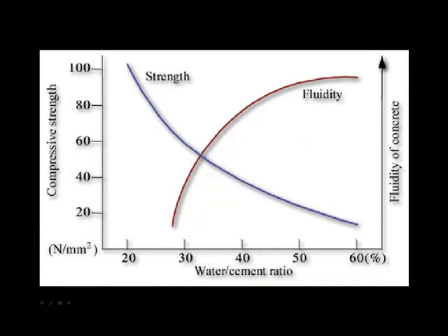Here's a chart that shows the effect of adding water to concrete. The blue curve begins with the highest strength and falls off dramatically as you add water. Adding water is something that you must control. And if you add too much water, you've sacrificed the strength of the concrete, and there's no undoing that. Once the water is in there, you're going to use that concrete and get poorer results.